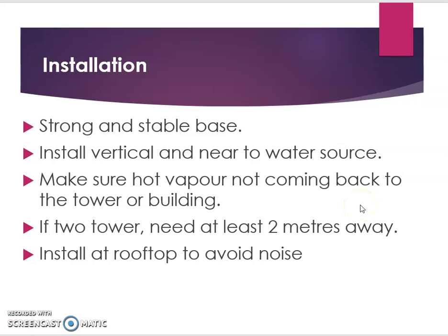And you must make sure that we install the cooling tower in a vertical way and not in a horizontal way, because I've never seen a cooling tower installed horizontally, since usually we want to reject the heat high into the air. It also has to be near a water source, because of the loss from the cooling tower's rejection, the vaporized water. That's why we also have to have a backup water tank to cover the loss. So that's why we have to be near a water source.